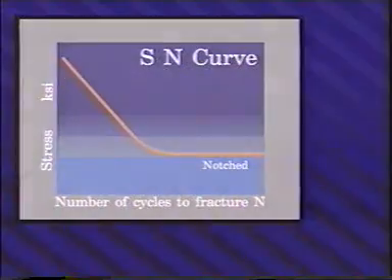In pure axial loading of a simple uniform beam, the stress is uniform across the cross-section of the beam. Therefore, a fatigue crack may, at least theoretically, initiate at a discontinuity within the member. However, it usually initiates at the surface.